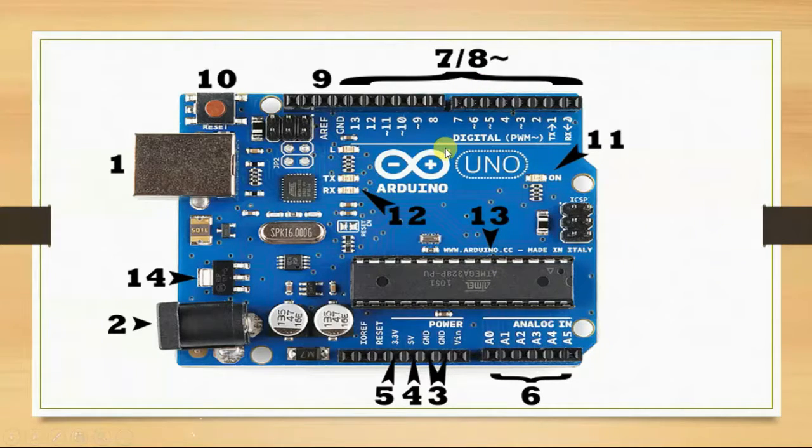You can take any pulse width modulated output from these pins. PWM you actually use to control servo motors, and for dimming your LEDs, lights, all those kind of things you can do with the PWM. We'll see later on what is a PWM. Then it is having actually 2 pins, TX pin and RX pin. Then we are having analog reference pin over here, and actually we will not use analog reference commonly, but in special cases we can use this analog reference pin also.